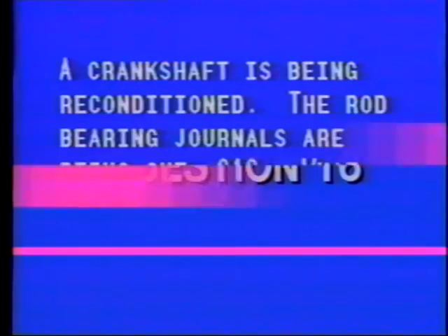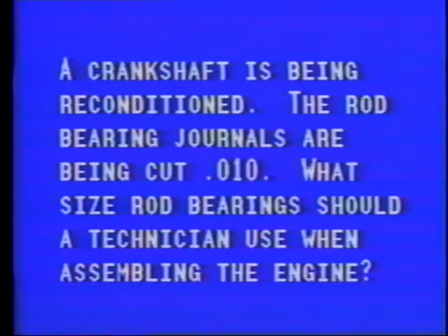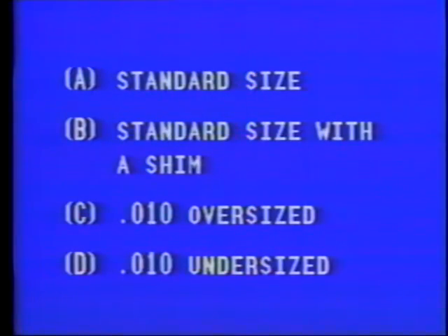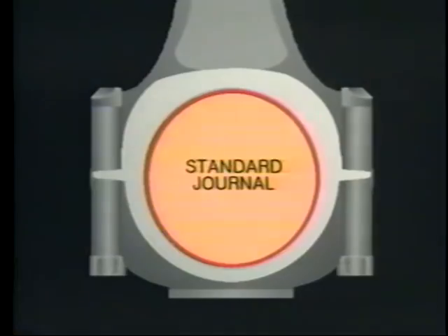A crankshaft is being reconditioned. The rod bearing journals are being cut 10/1000ths. What size rod bearings should a technician use when assembling the engine? A, standard size. B, standard size with a shim. C, 10/1000ths oversized. D, 10/1000ths undersized.